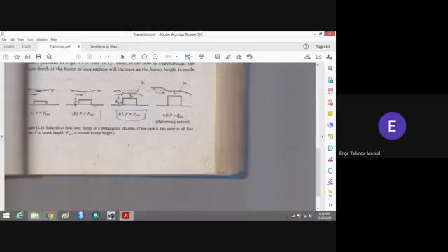So if you want to have the critical depth of the flow over the weir, and you want to have a control section, then this height of the hump is enough. This is the enough height of the hump you have. There is no need to have this height of the hump, because in both the situations you have the critical depth of the flow. In both the situations you can have the control section.